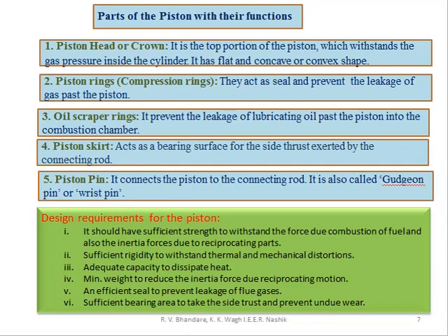At the same time, it should have minimum weight, so it has minimum inertia force, which actually affects the reciprocating motion. Next is an efficient seal to prevent the leakage of flue gases, and sufficient bearing area to take the side thrust and prevent undue wear of the components.